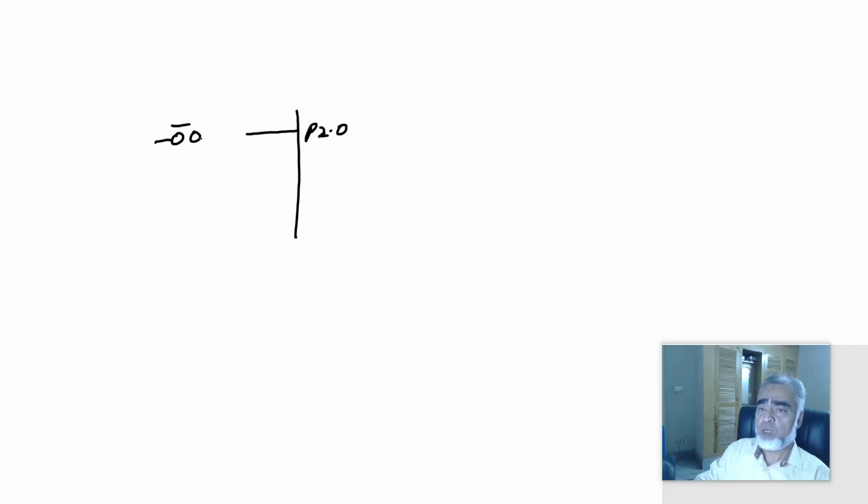We can connect this switch with port 2.0. Now we can make this input active low or active high. If we want to configure this input as active low, then we'll connect the next end of the switch with the ground, like this.